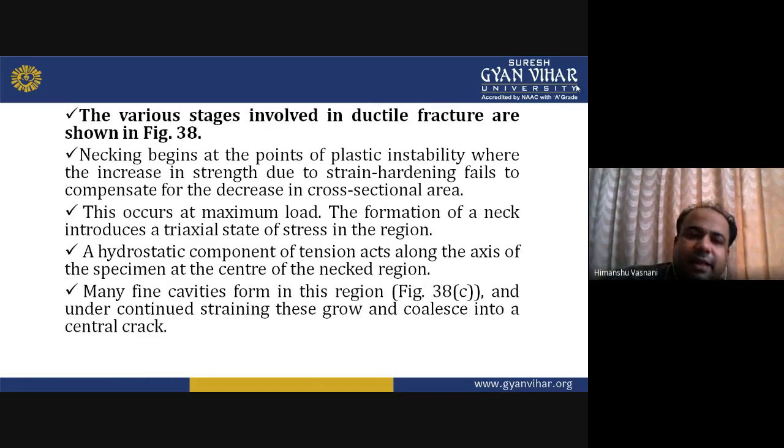Necking begins at the points of plastic instability, where the increase in strength due to strain hardening fails to compensate for the decrease in cross-sectional area. Now this occurs at maximum load.